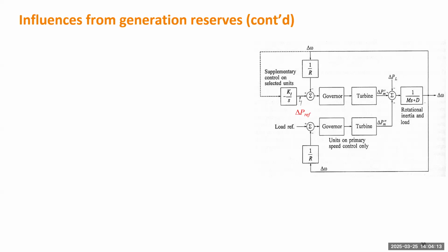Another, opposite scenario is that you suddenly decrease the load. You disconnect, say, one substation with 100 megawatts. This unit is in AGC, so it will decrease its output by 100 megawatts. But in some cases, it has a lower limit and cannot decrease by 100 megawatts. Then it will just stop there, and the frequency cannot go back to 60 Hertz. You need some other unit to give you that room. So each generator connected to the governor and AGC has an upper limit and a lower limit. As long as the upper room and lower room are large enough to cover the load change, even if you only have one unit in the AGC, eventually the system will go back to 60 Hertz.